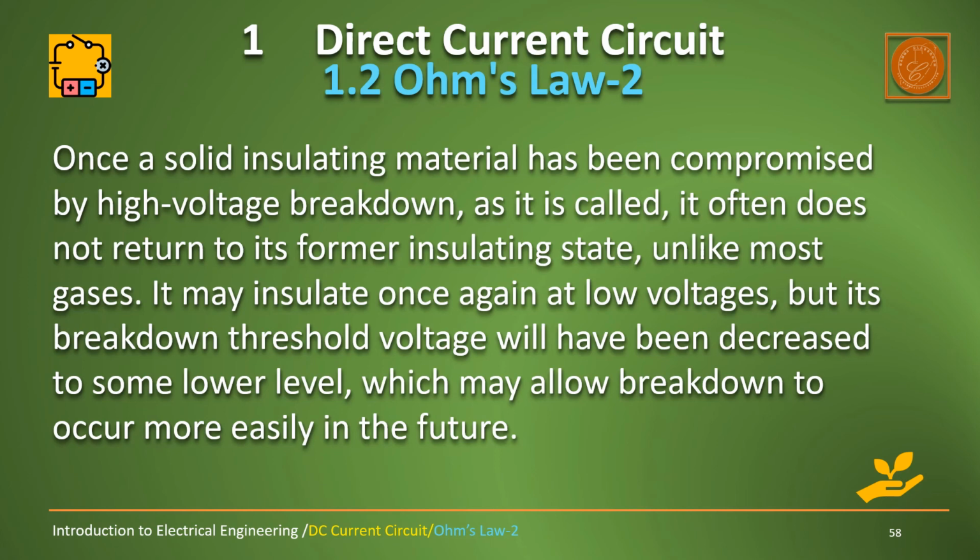Unlike most gases, it may insulate once again at lower voltages, but its breakdown threshold voltage will have been decreased to some lower level, which may allow breakdown to occur more easily in the future.